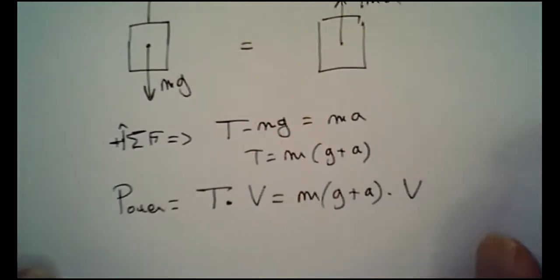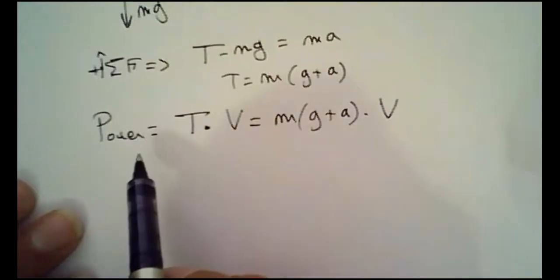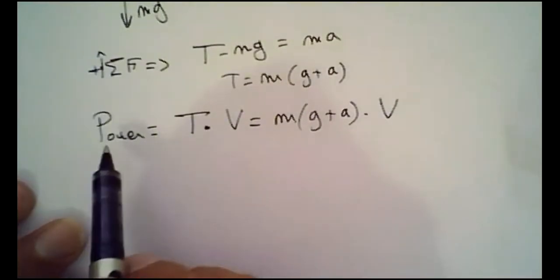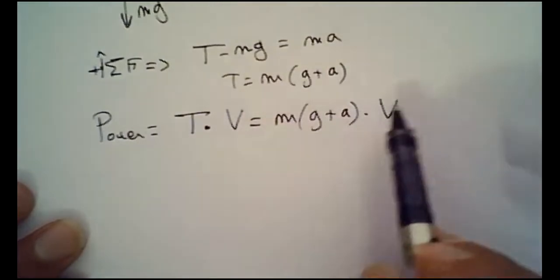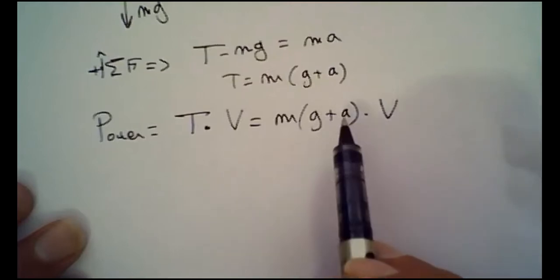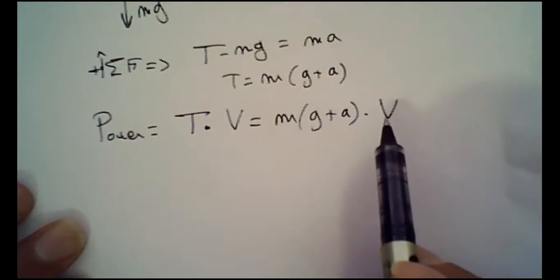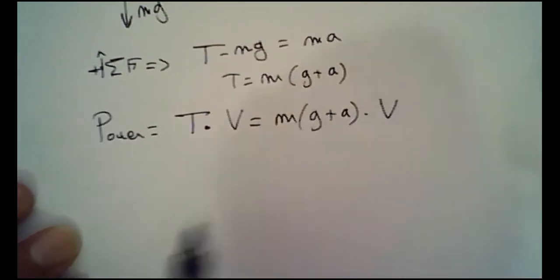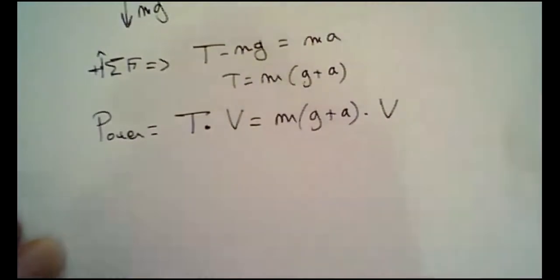And then what I want to tell you guys is that since we described power, the next thing we're going to talk about is efficiency, right? When I'm looking at the power, this is the power needed to create or sustain this movement or this acceleration, and obviously the weight of the elevator, and to move the elevator at that velocity. So this is the output power of the system. This is the raw mechanical power that I need to deliver to the system.